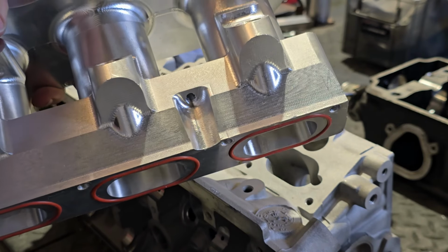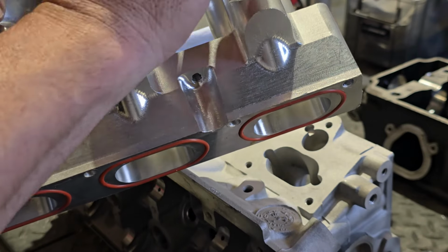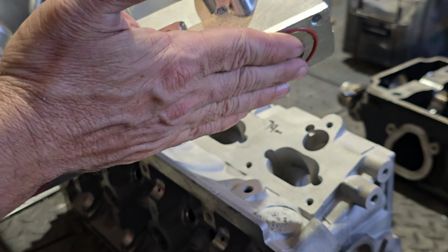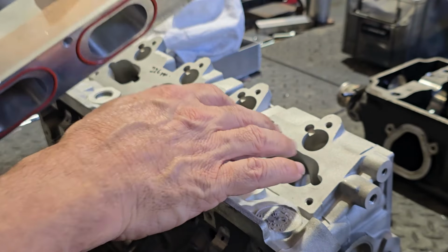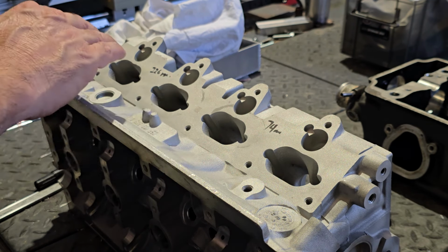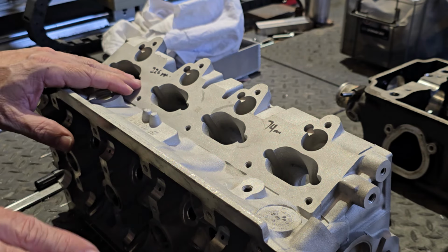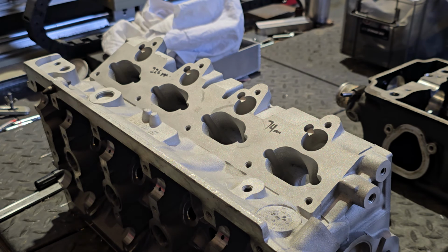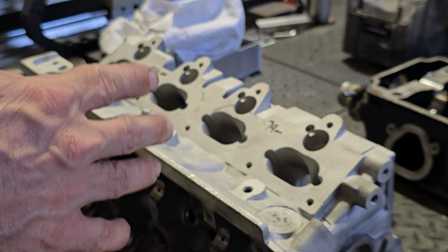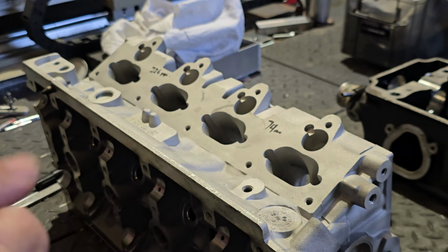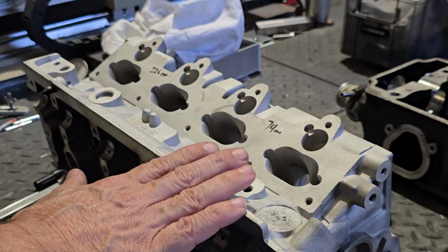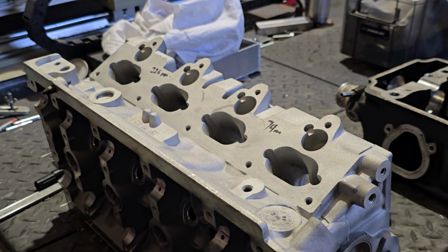Now I've gone to the bell, even though this radius will actually make it look about a half inch shorter. I've gone from the face to the bell, and he's going to also put a 3mm spacer, an insulator, in here. So that brings us up to about 226 plus our 3. So let's say 230 millimeters in total induction length. So let's do some math.